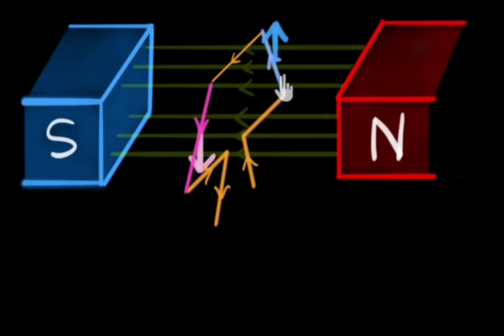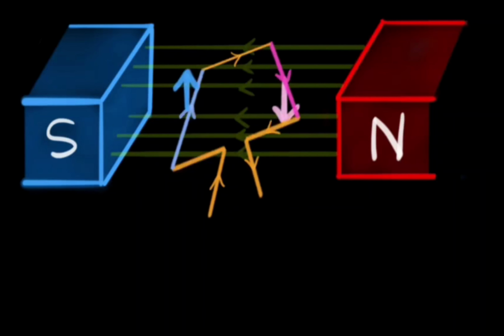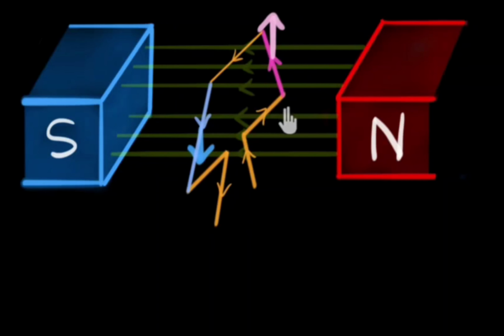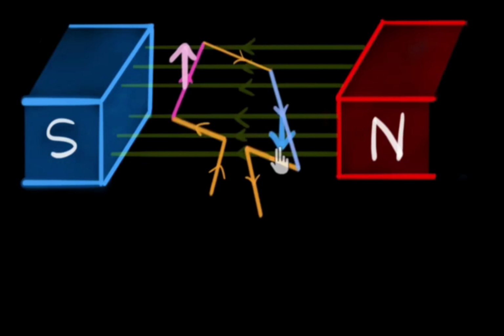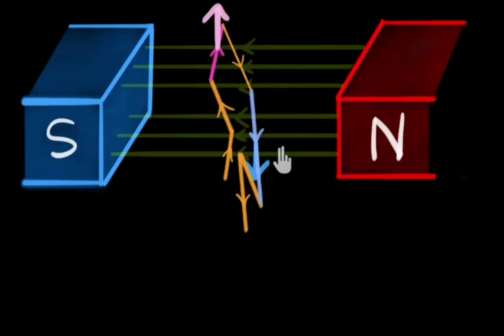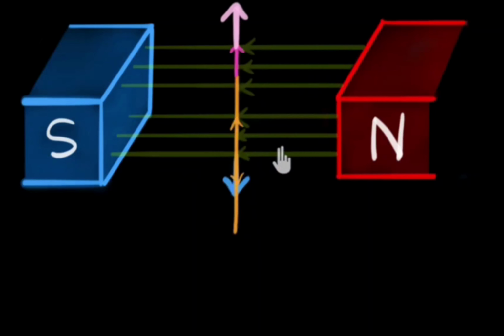It may be noted that a single turn armature coil gives an EMF quite small in magnitude, therefore the coil employed in commercial machines consists of several turns in series, thereby increasing the magnitude of the EMF, which is directly proportional to the number of turns in the coil.